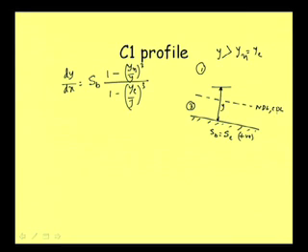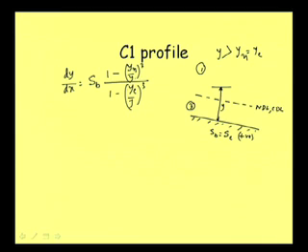Well, if these are equal, then we have some interesting situation here. Let us first see about the rising and falling type: yn is less than y and yc is also less than y, both are equal, and so these two ratios in numerator and denominator are less than 1, and that is why 1 minus something less than 1 will be a positive term, and this is also a positive term, and SB is positive.